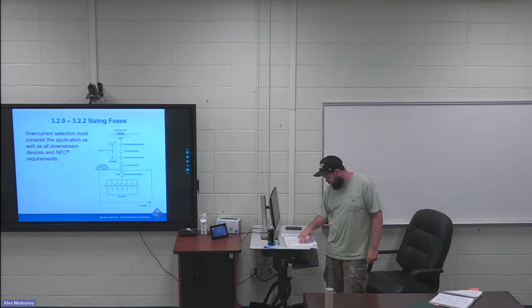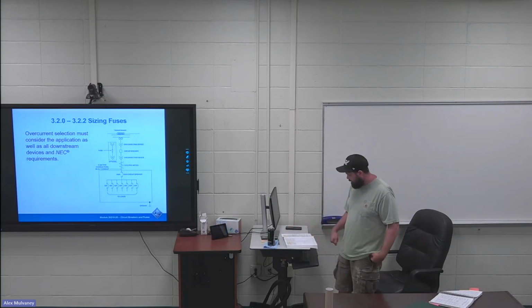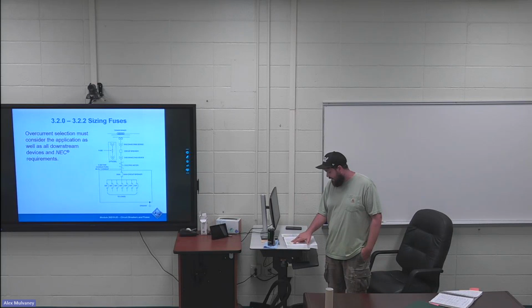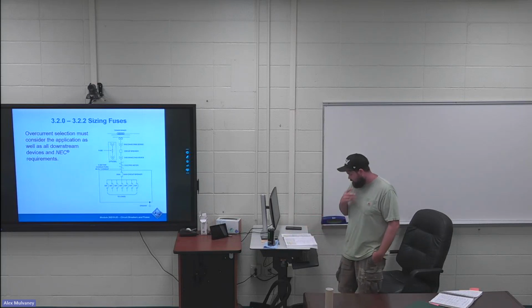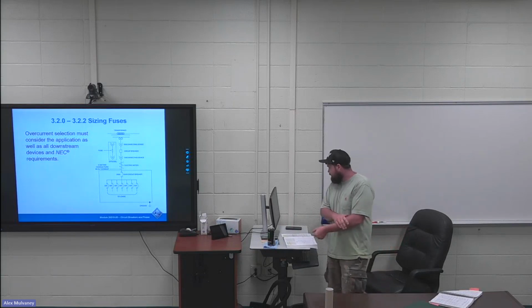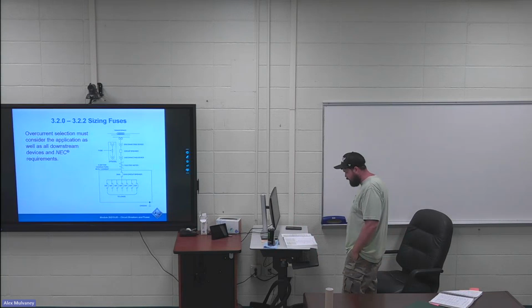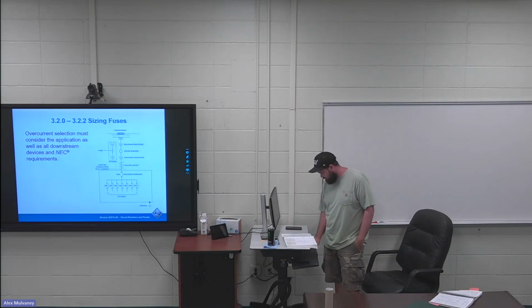The next paragraph, the first full paragraph on page 20, is highlighted. When sizing fuses for a given application, a schematic drawing of the system will help tremendously. Such drawings do not have to be detailed. A single line schematic will suffice, such as the one shown in figure 13 or up on the board. So that shows you want your stuff coordinated, which is what we're going into next.